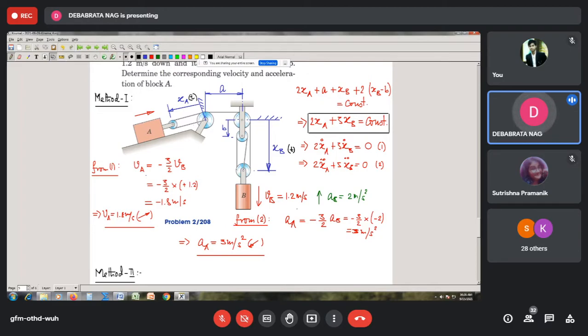If you look at this pulley here, we note that the string of this is connected to the center here. So this is where the string is connected, which means all points on the string are going to be fixed. So this pulley will try to rotate with respect to this point. Correct? So either the rotation will be in the clockwise direction or in the anti-clockwise direction. That will define the sense of the motion of this block A.